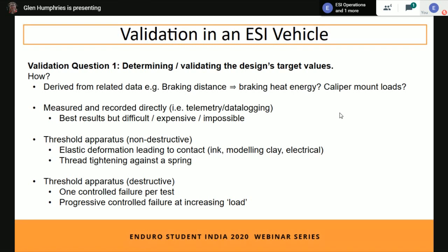So you go testing, driving around, loading it up, you come in, it's loaded this thread to a certain point. You then basically take it off the car, take it to the workshop, take it apart, and then rewind it by hand with some sort of controlled torque. For example, lever arm and weights, until you've reached the same point that it was on the car, and voila, you know how much torque it saw, you know how much torque it experienced, in order to get to that point, and you've now got a good accurate measure of how much torque is going through there. And the nice thing about this is it's, as we'll mention a bit later with trying to theoretically calculate some values, is this actually captures things like impulse loading.